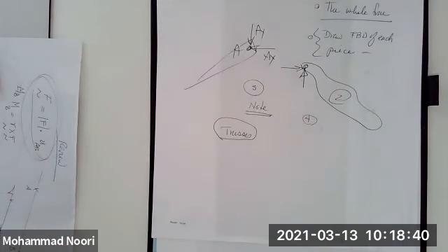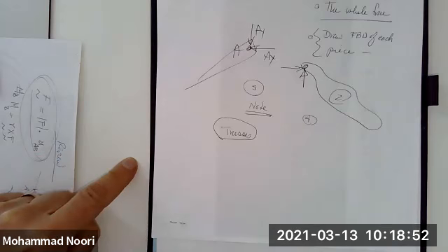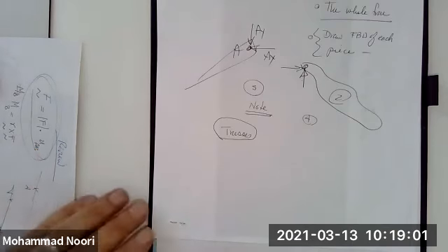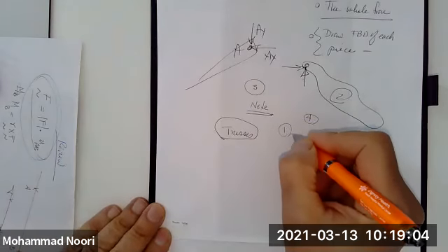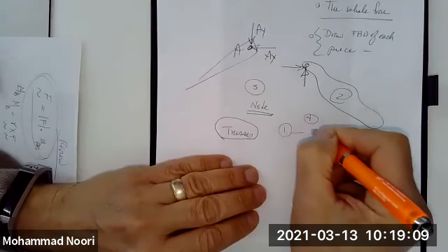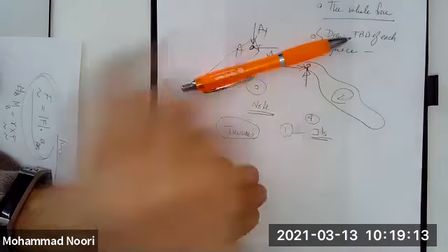So what does that mean? That means if you consider a joint of a truss, forces that are coming from those members to that joint are acting along that member that you have removed. So in trusses, you have two objectives. Either you are asked to find all the member forces. In that case, you use method of joints if you're asked to find all member forces.